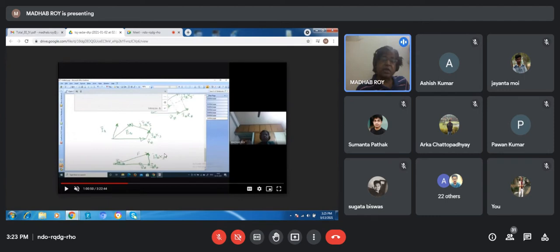reactance drop, the synchronous reactance. You know that a synchronous machine has a reactance different from all other machines, because in a synchronous machine it is called synchronous reactance. That involves another concept. So synchronous reactance is related with the armature reaction. You have to remember, there are different types of armature reaction. That armature reaction is incorporated in the form of a reactance. So that is not available in any other machine. This is only available in the synchronous machine.